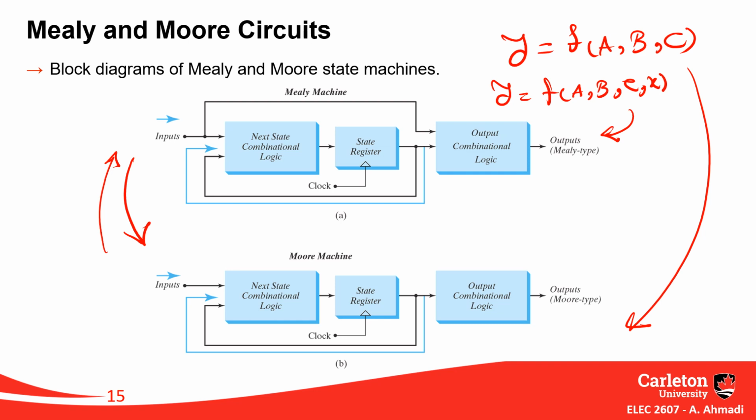Okay, that's why we end up with a Mealy machine. It doesn't mean every minimization will make your design a Mealy, but what we can say is that two machines with the same behavior, with the same original description, if you implement them in Mealy or Moore, normally the Mealy machine is simpler and cheaper to implement. But it has a problem with synchronization because it follows input as well as your current state.